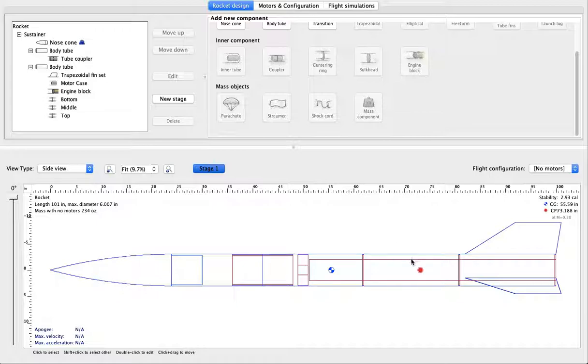Now, I know we're skirting around the motor, but I want to introduce this one concept really quick. It's called a boat tail. Now, a boat tail, you can see this little distance right here. It's going to get some eddies from the air. The form drag is really not going to like that, and it's really going to kill our altitude if we're trying to go high, right? So first of all, we want to prevent that, and boat tails do that.